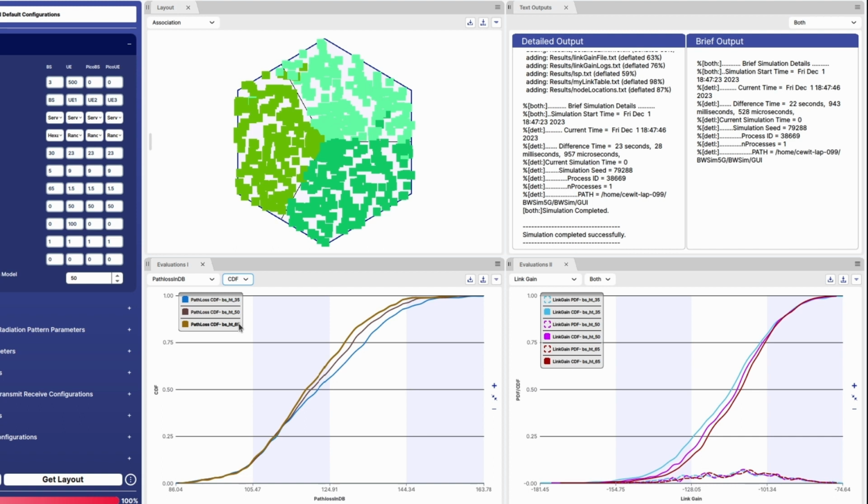Why is this so? When your base station is located at a higher elevation, the transmitted signal is less prone to encounter a scatterer that contributes to path loss. Based on this, the observation of higher elevation, lower path loss can be explained.